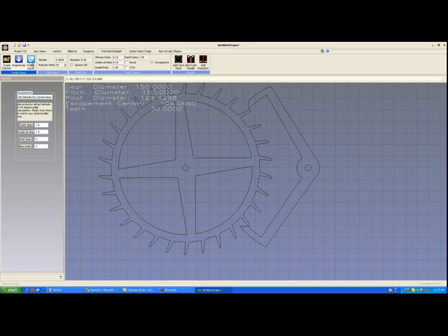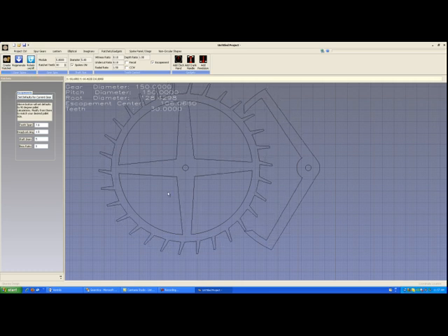So as we can see, the same thing happens on the bottom. The tooth is now pushing on the impulse face, causing the pawl to turn counterclockwise and adding energy in that direction. So in essence, we really just need to worry that the teeth of the deadbeat are hitting a locking face when the escapement starts to rotate, and that the pallets do not get hit by the teeth. If the pallets are hit by the teeth, we're going to cause damage to the pallet face, and you're going to end up doing repairs to your clock.